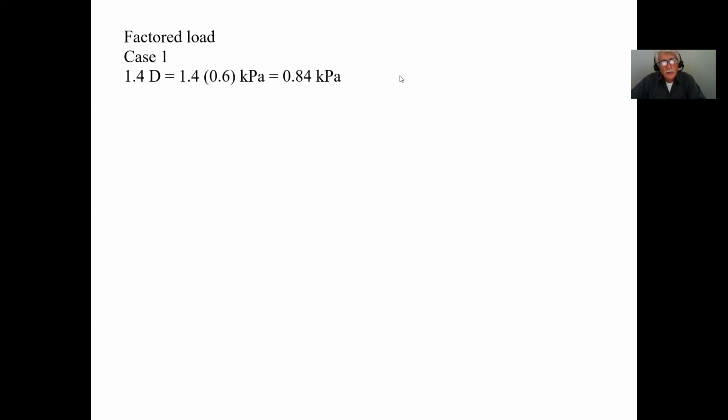And that's it. So now, what we always do is we take our specified loads and we turn them into design loads. And by design loads, we mean we factor them. And of course, case 1, okay. I'm doing this so that you remember that sometimes the dead load can be substantially high. If the dead load ever happens to be 10 times greater than your live load, believe it or not, your case 1 will govern your design.